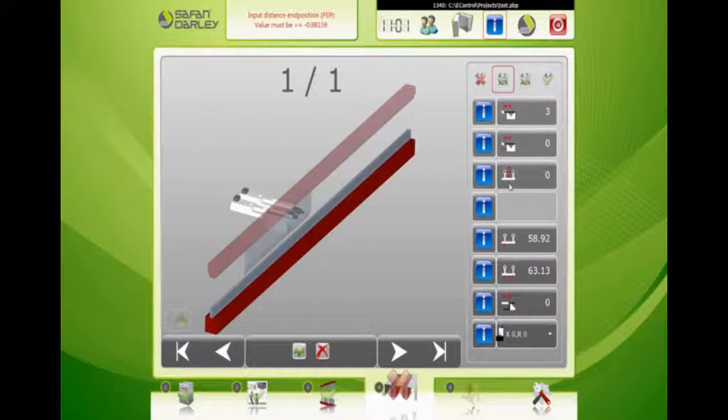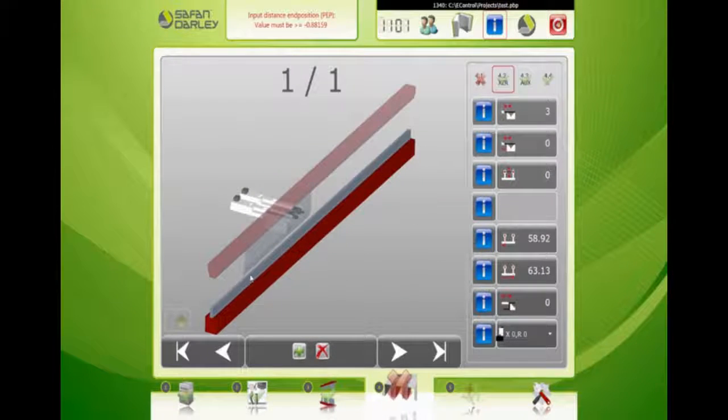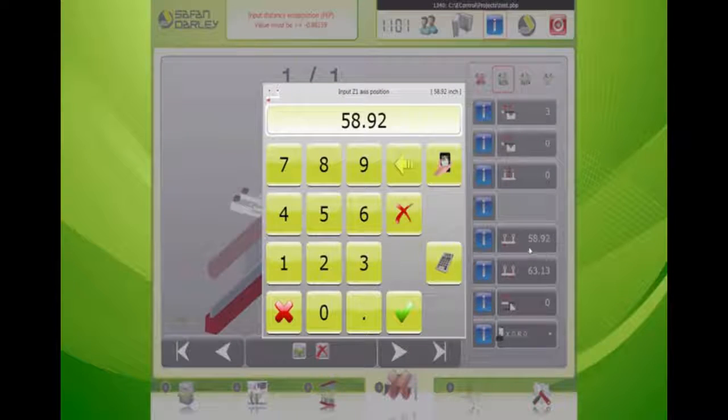This R-axis is at 0, meaning it's at the height of the tool, so it knows where it's at. So if it's at 0, it means the fingers are going to be at the height of the lower die. So I'm going to leave that be. And position of the fingers. Oops, let's close this out.